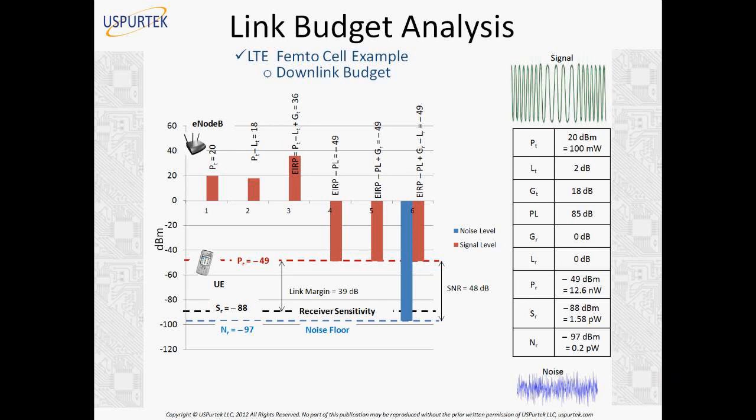Okay, there's another question here. In any particular band, are there a fixed number of users associated in TDD? Well, yes, of course there will be a fixed number of users, because every user will be using some resource in the frequency. In TDD, there is a number of time slots, right? And when the time slots are filled up, then of course you cannot accommodate too many users in that.